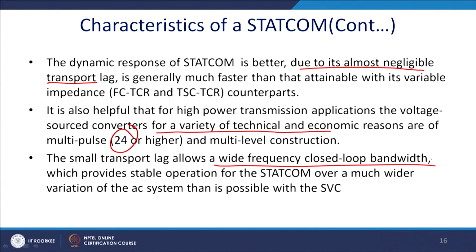The small transport lags and wider frequency closed loop bandwidth provide a stable operation of the Statcom over a wide range of variations of the AC system possible than the SVC. So, it is quite superior to SVC.